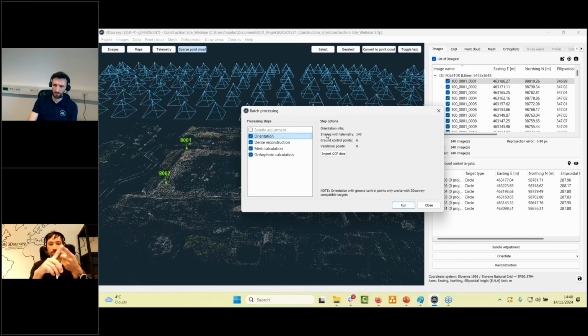This is the first important point. The second important point here is that you have your telemetry data and ground control points in the same coordinate system. So the ground control points need to be at the exact height, in the exact coordinate system as your drone data, and with the help of geoid, grid and shift files, this is possible. But of course, you need to have an RTK drone, okay? And then you can also perform the orientation here automatically.